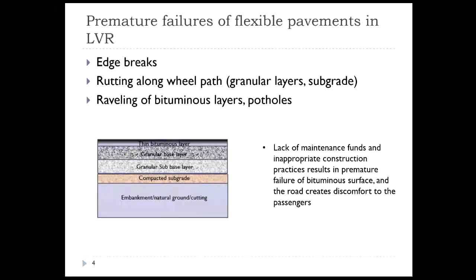If you don't do routine maintenance, your pavements will continue to deteriorate to very bad levels. So in the case of low volume roads, we have all these unforeseen things. Lack of maintenance funds and inappropriate construction practices will result in premature failure of our bituminous surface, and this creates discomfort to the passengers.